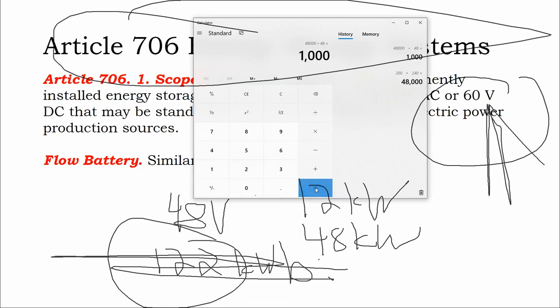Instead of a 200 amp service, we have 1,000 amps coming out of that battery. That's parallel runs of incredibly thick battery cable. Now, you can find lead acid batteries that are rated for 1,000 amps output, but your battery cable sizes are getting into the size that you'd use for utility scale facilities. With incredibly high amperage, you're spending too much on your cable.